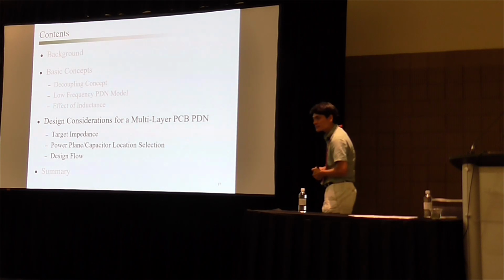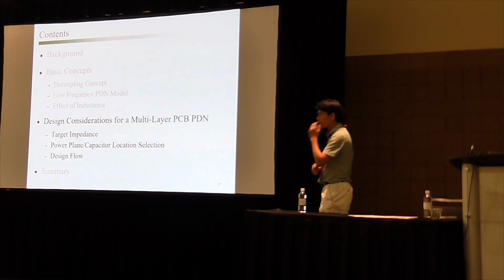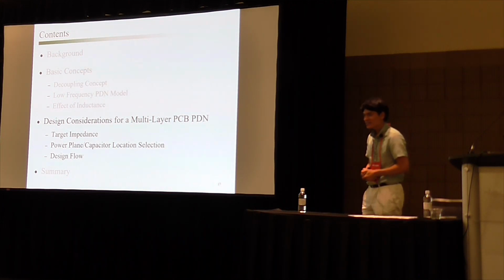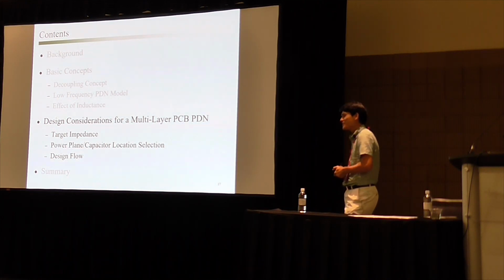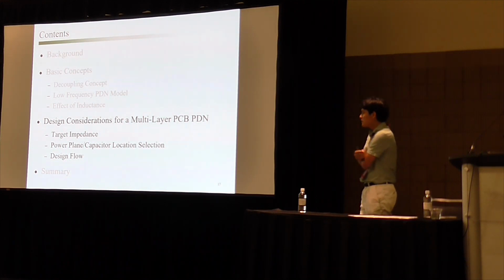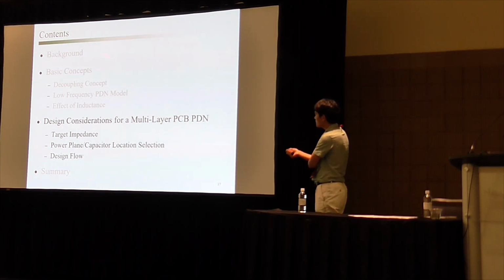So the only hope of providing high frequency capacitance for impedance is just the distance between power and ground of the PCB. That's what it sounds like. Is that right? Which makes it very difficult, because these days you cannot make the board thin, and that increases the cost, doesn't it? There's a couple of ways to reduce this inductance. Here, we're only talking about the decoupling capacitors. Yeah, that's why I introduced that concept.